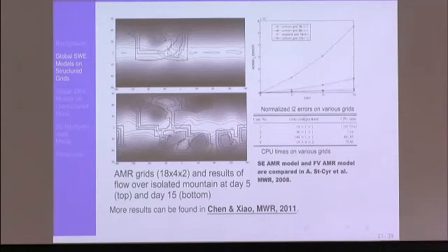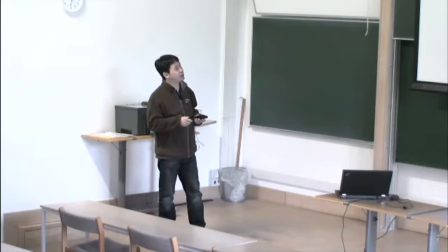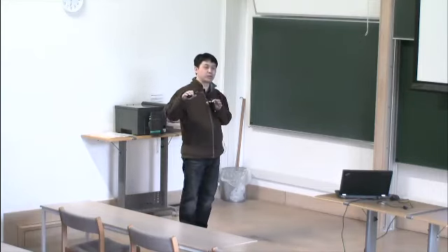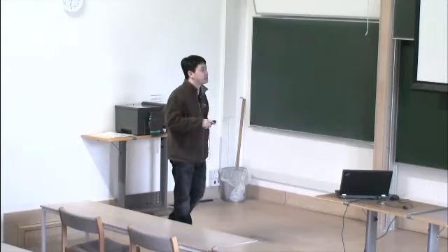The spectral element method produces a similar result, but if we use a finite volume model, the normalized errors on the AMR grid may be much larger, maybe approaching this point. So from this result, I believe the local reconstruction is also useful for improving the accuracy on the AMR grid, to reduce the errors due to the different resolutions on different levels.